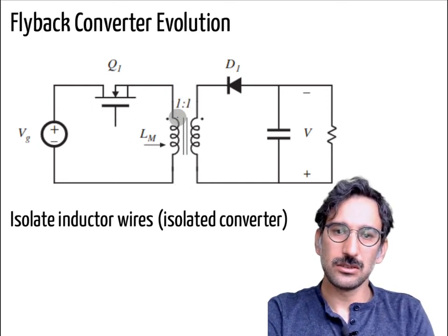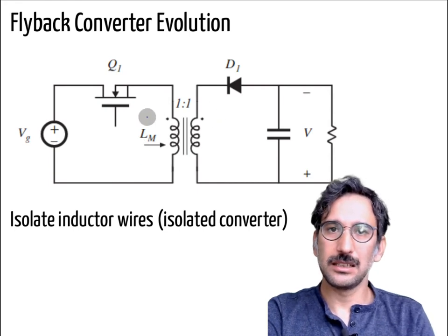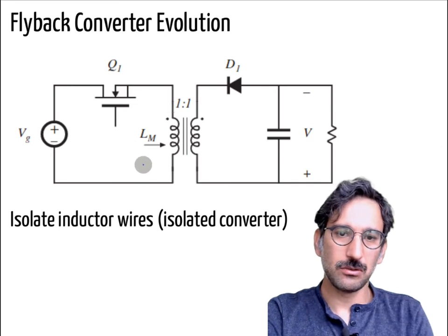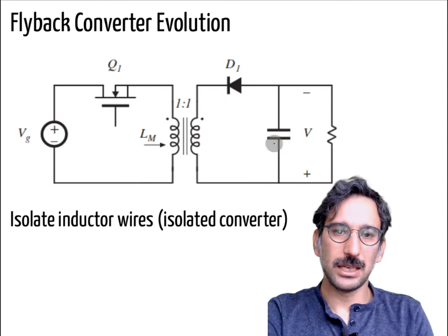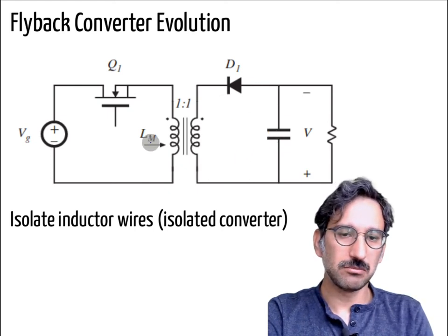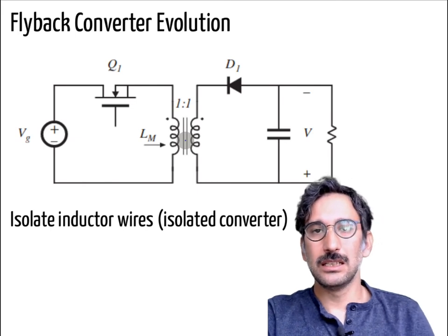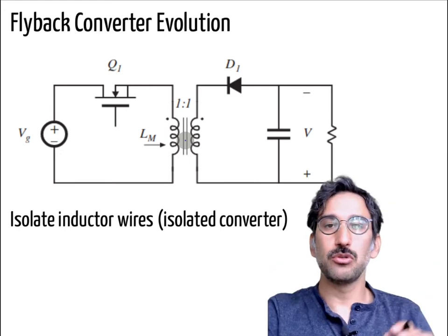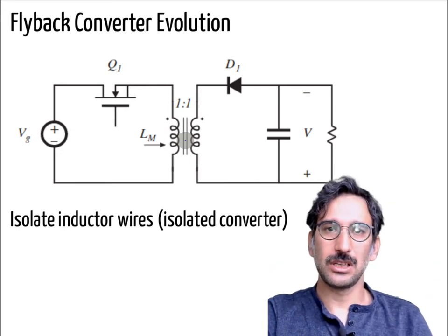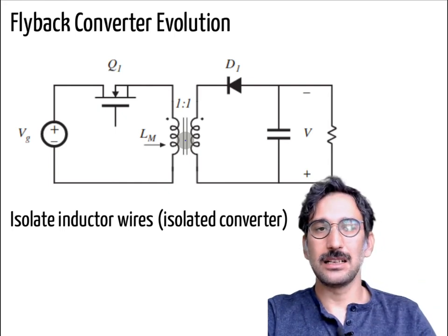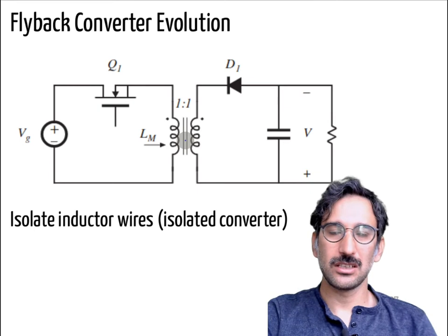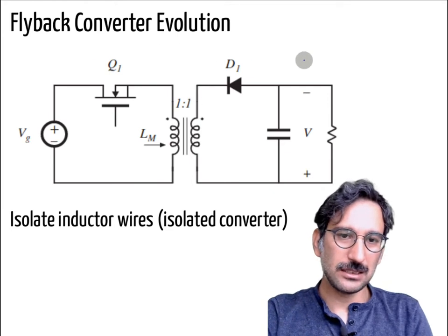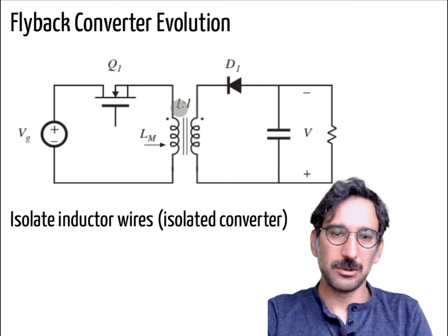Let's say this is an ideal transformer for now, and whenever you close that switch, you will have some current, and the same current will pass through here, right? But then, we know transformers only work with AC, not pure AC, but it should be stated like that. If you give a constant DC current, the flux in the transformer increases and saturates the core. Okay, that is how the flyback converter evolved, and we will derive it.